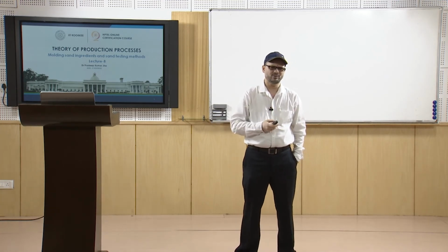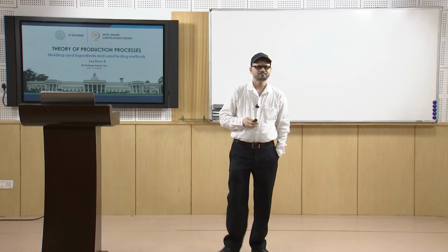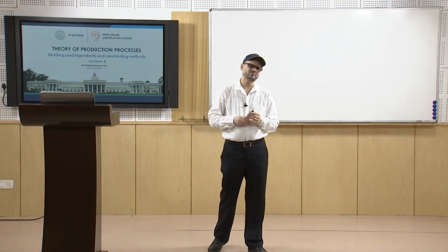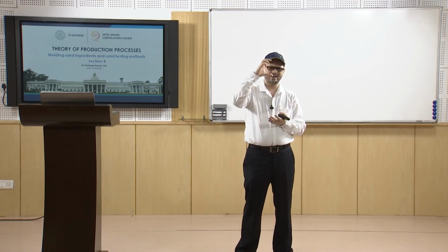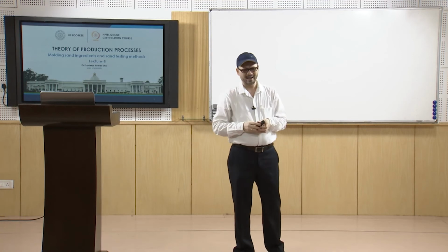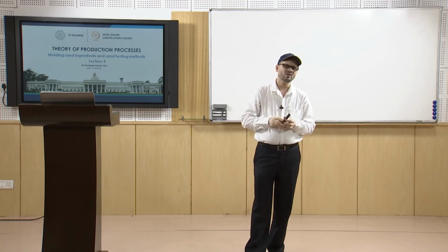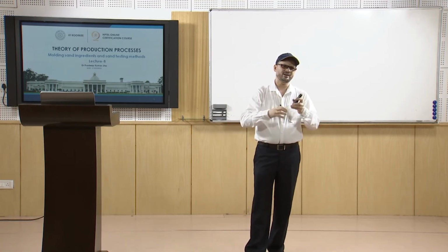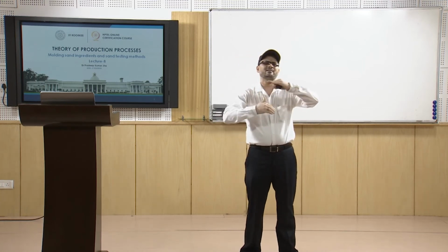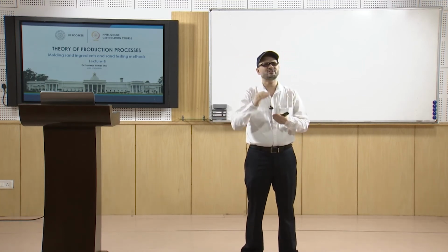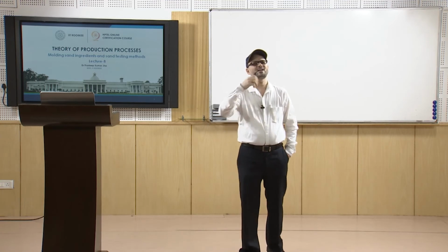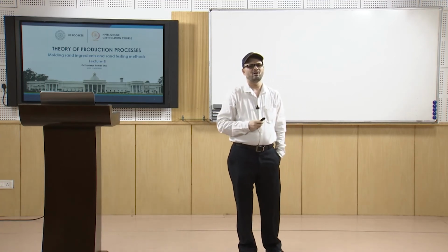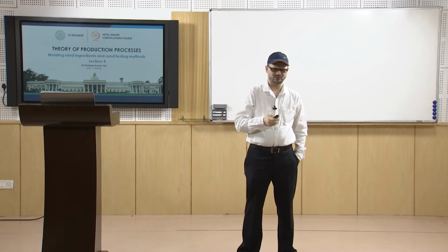Based on some basic chemical or physical properties, we have different kinds of tests where we normally measure the bulk properties. For many cases we have the standard specimen, a cylindrical specimen of 2-inch diameter and 2-inch height, prepared from the sand by a certain standard method of ramming to get this kind of shape, and then you can do the test on this specimen.